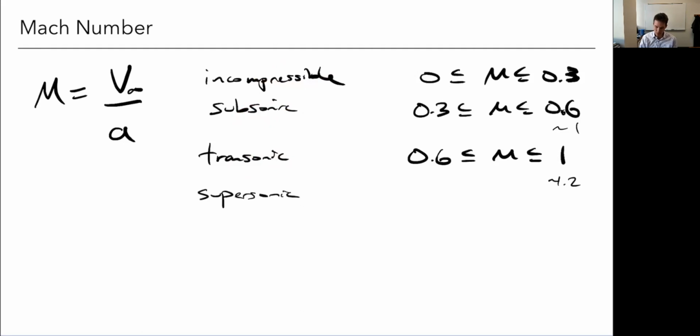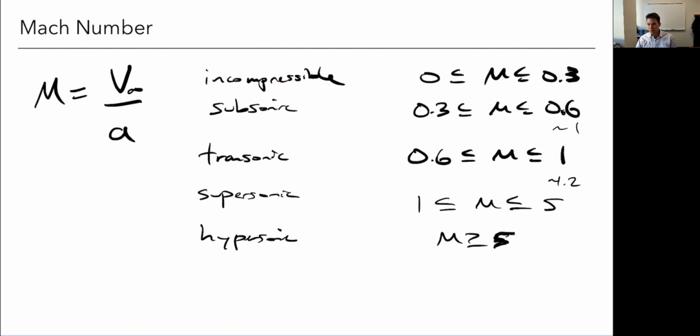And then supersonic, again, strictly means above Mach 1, but we usually cap it around 5, and above 5, we'll call it hypersonic. Again, nothing magical changes at 5, just a rule of thumb. And the reason why we do that is that around that point, the change in temperature from the extreme speeds becomes very significant.